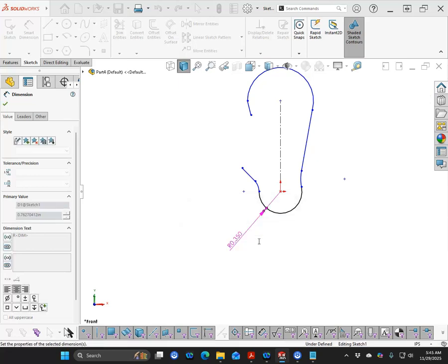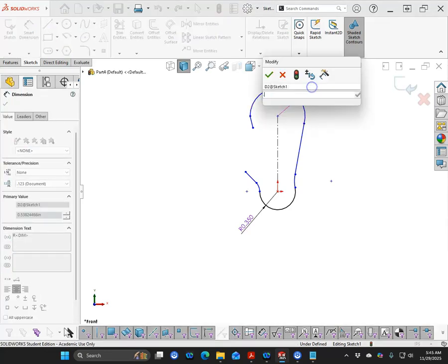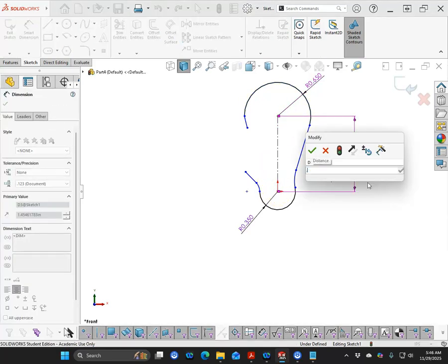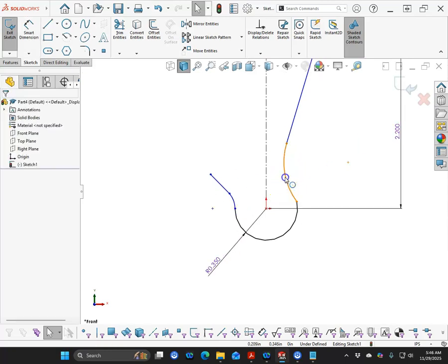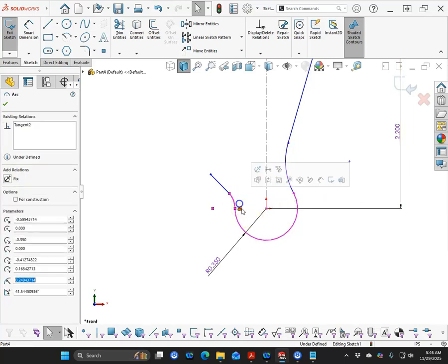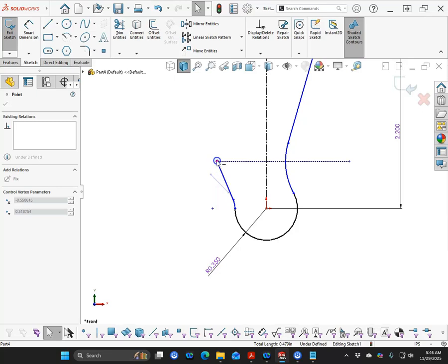All right, so let's get some dimensions on this and start bringing it in. So 0.35, and it scales 0.65, and we have, do we have an angle? No. All right, so for this, we'll do 0.45 plus 1.75, get the overall dimension. So just the way that moved, I can tell I didn't get a tangent there. And we didn't get a tangent there, so let's bring that back.